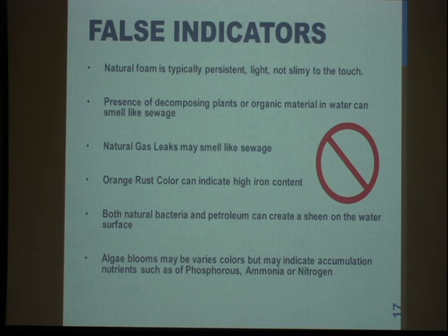Sewage smell, sometimes, again, if there are decomposing plants and organic materials in water, especially in the springtime, it might smell like sewage right when it kind of turns over. Natural gas leaks smell like sewage. Sometimes when you open up a drain line, you might think it smells like sewage, but I've seen this in the field, where it's a gas leak near it, so it goes into the drainage structure, and it smells like there might be sewage in there.